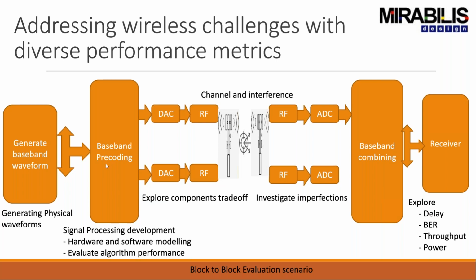What you can do is run the algorithm in the software, look at the blocks, and evaluate their performance. You don't need to wait until you complete the transmitter or RF chain. You can evaluate the algorithm performance in each and every block, and then it moves forward to digital to analog and then RF chains. Over here, if you want to have a trade-off or check what happens if the power is different, what if we give the power as 10 milliwatts, or 10 watts, you can think about it.